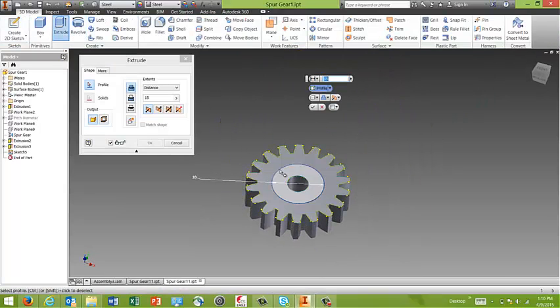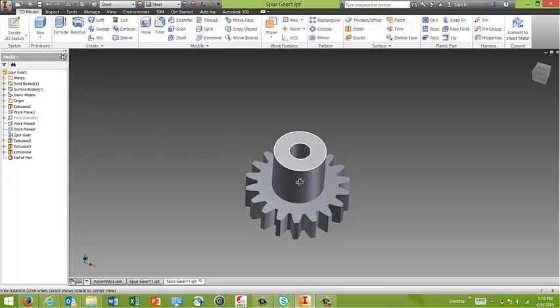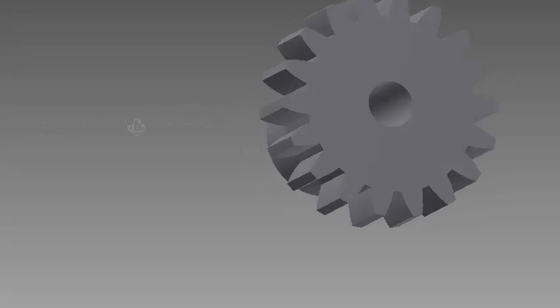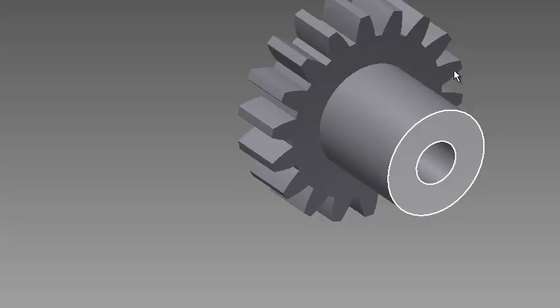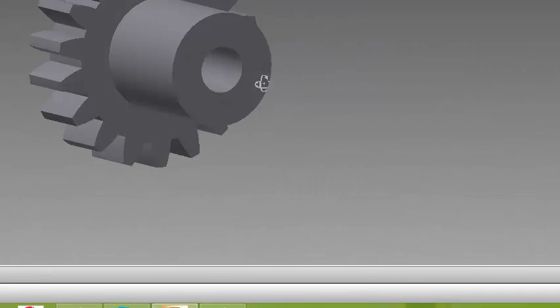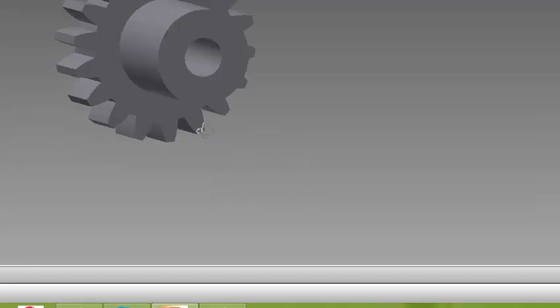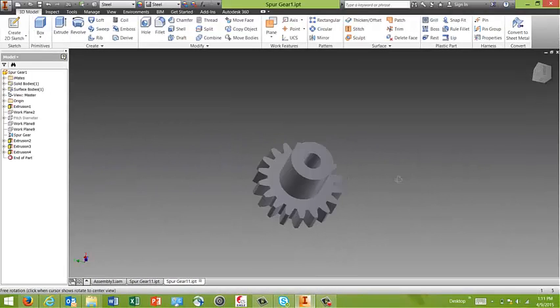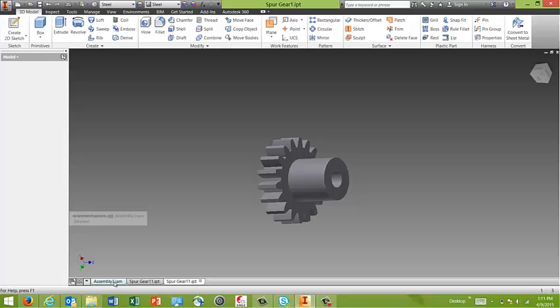And when I extrude, I could extrude this donut out. Have it 10 millimeters, and I have created a boss on the gear. You could then create your cross holes so that you can insert your press fit M3 nut, then you can insert a set screw to lock onto the shaft, so that when the gear rotates, the shaft rotates as well. So you could do a lot of post design on the gears that were generated earlier on in the assembly file over here.